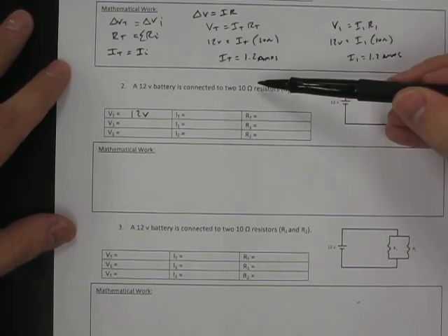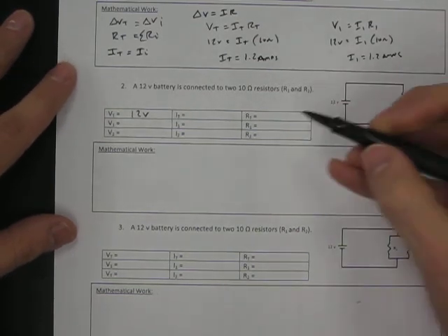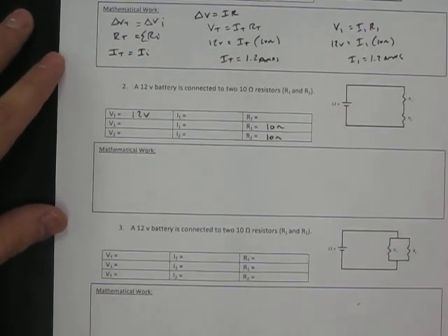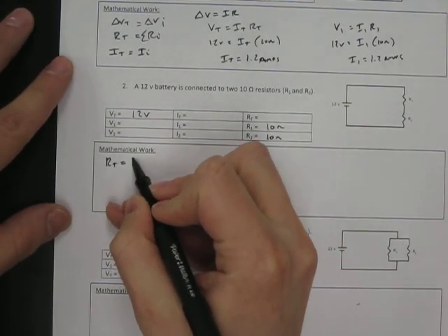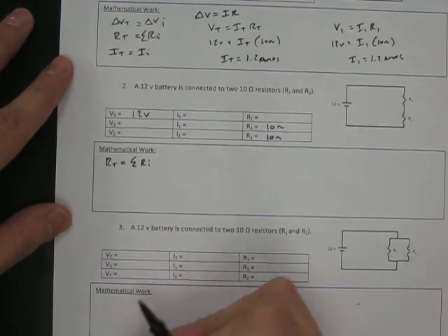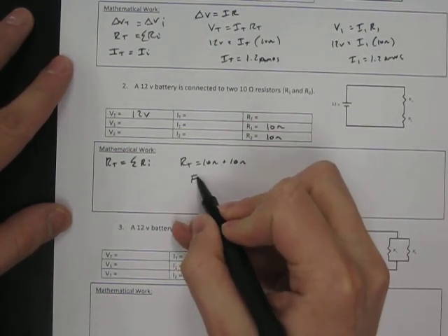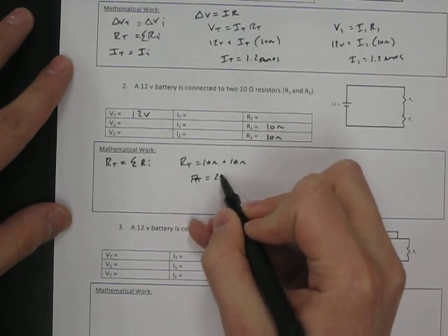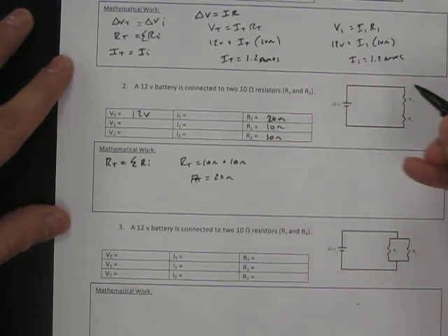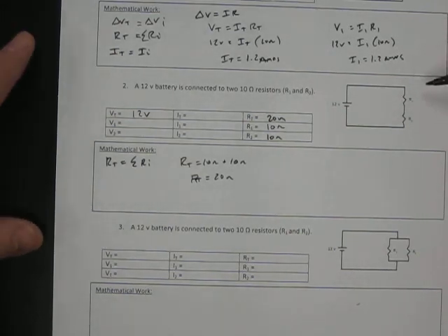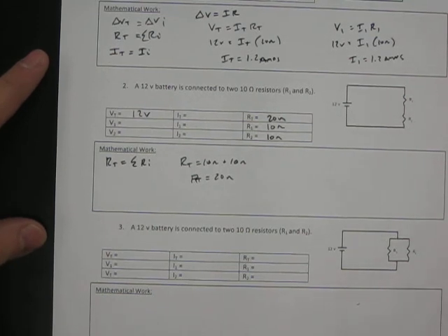Other things that we know is we have two 10 ohm resistors in here, and so we're going to make R1, well, we know that's 10, and we know R2 is 10 given in the problem. And like before, we said that the total resistance is just the sum of all the individual resistors. In this case, RT would be equal to 10 ohms plus 10 ohms, or our total resistance would wind up as 20 ohms. So what we're showing is that as you add resistors in series, the total resistance goes up because these charges have more resistors and things that are trying to slow down current in that setup.